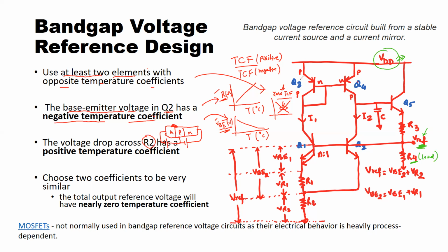So what I'm doing, I'm using the transistor Q3 and Q4 in a current mirror configuration using PNP transistor. So this is my current mirror. Basically I am using the VDD and the diode connected mode of the PNP to generate the I1, or input current, or I reference. We have a lot of video tutorials on what a current mirror is and how it works, so refer to those if you are new to this.